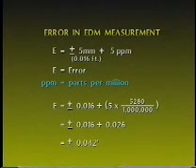This proportion is equal to 0.026 feet. The total error would therefore be plus or minus 0.016 feet plus 0.026 feet, which equals plus or minus 0.042 feet for the 1 mile line. This error is a standard error of the mean value and is therefore a measure of accuracy.